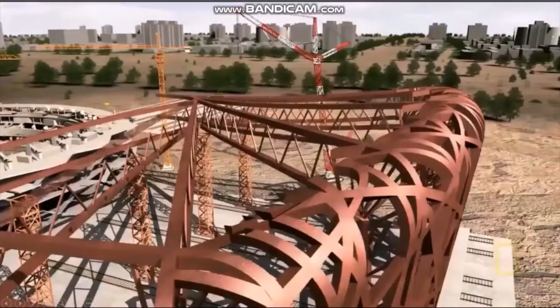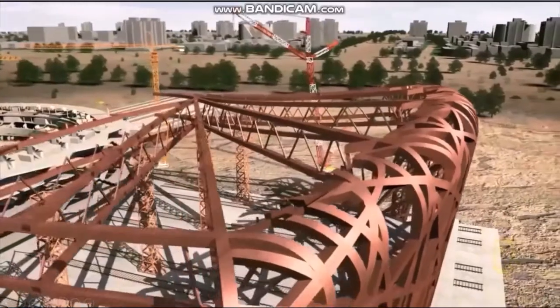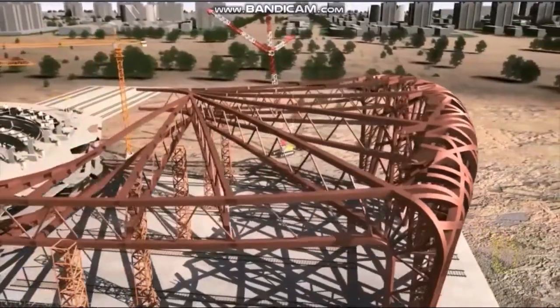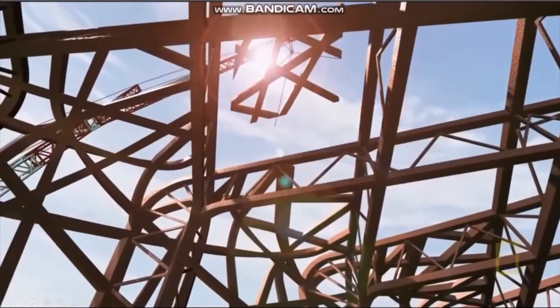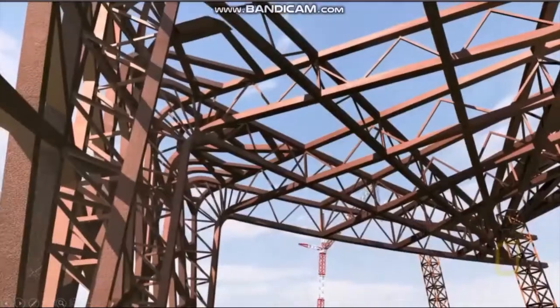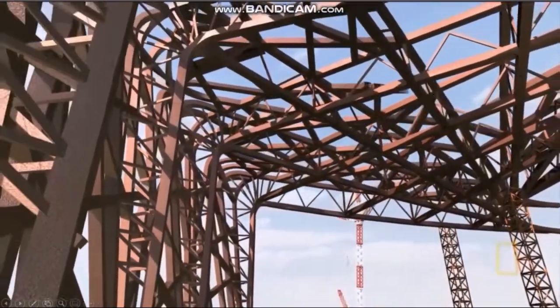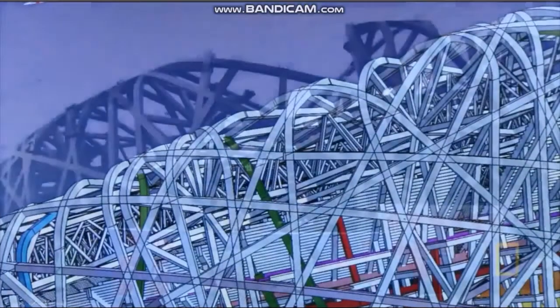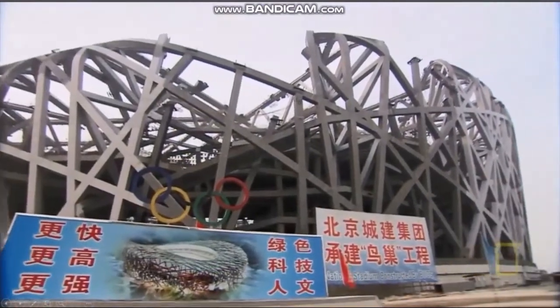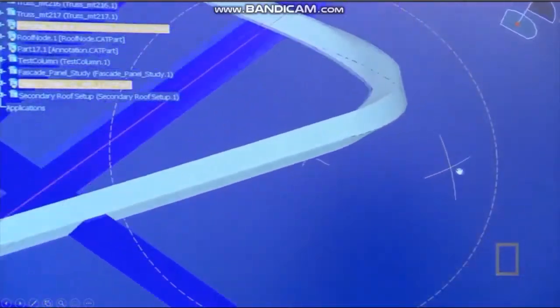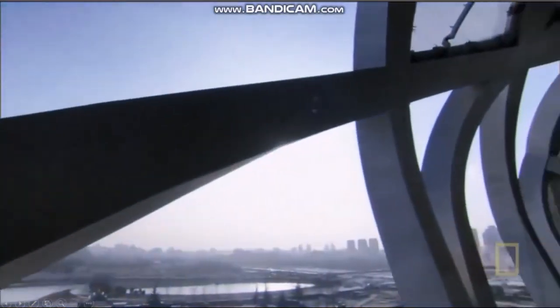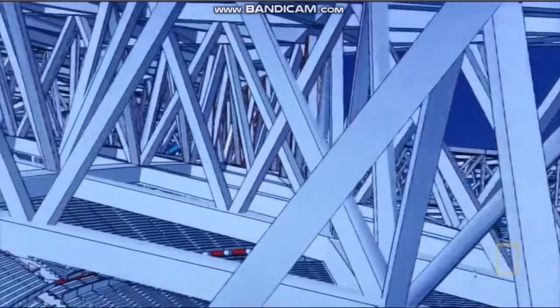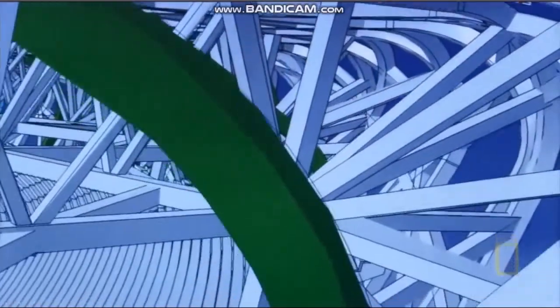The very long 330 meter span caused the seismic design to be significantly different in several ways from that of typical tall buildings. For instance, limiting interstory drifts and the detailing for ductility were insufficient for the bird's nest roof structure. It could have collapsed straight downwards without lateral sway, due to damage to its gravity force resisting system from vertical earthquake ground shaking alone.